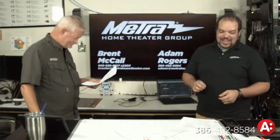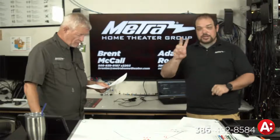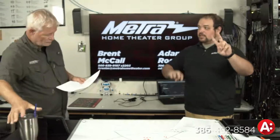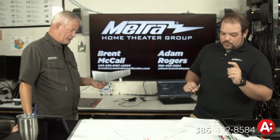No, so 802.3 AF is actually just the standard for regular PoE. Regular PoE requires 2 twisted pair. It actually is the alternative B, so that means we have 2 twisted pair for data and 2 twisted pair for power, which is why DC cameras work on it.